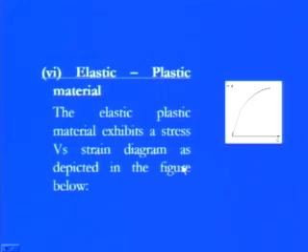Then we have the last one, which is pretty common. The ductile materials are generally there, showing mild steel, high carbon steel, and high speed steel. Generally we say these are elastic-plastic materials, meaning they show an elastic nature up to a certain point, and then a plastic nature, in which strain hardening is also available.